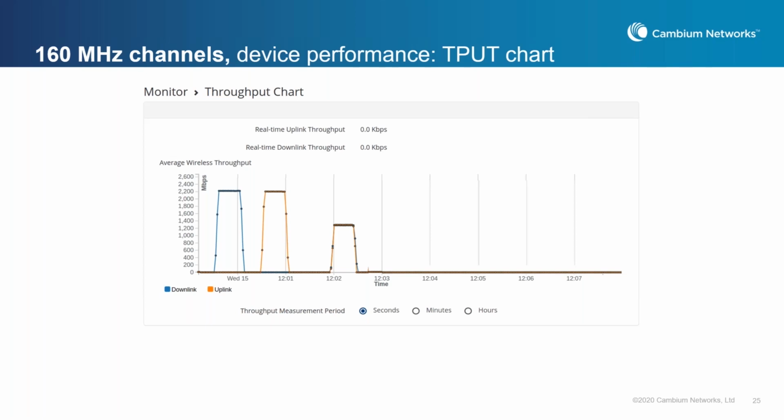Although they are quite small and not using a lot of bytes, they're using a lot of time, because you have a lot of subscribers, especially going to 120 subscribers. You're having a lot of subscribers doing acknowledgements, and each acknowledgement has the overhead for the data transmission. Although the packet itself is quite short, you still need a lot of time for those subscribers to send the data in the uplink.